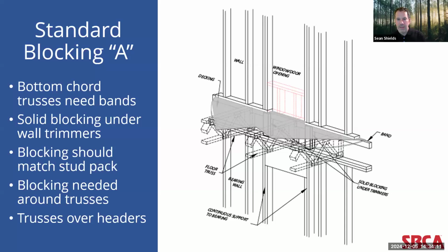In the case of this detail, we're addressing multiple floors where those forces are transferred through the walls, through an upper wall, through the floor to a wall below. Hence, the second thing I want to draw your attention to is for wall trimmers around rough openings, solid blocking needs to be installed in the floor cavity to transfer load between the floors. They may be hard to see, but right now I'm moving my cursor around the blocking that this detail is drawing your attention to, underneath the trimmers on either side of the rough opening.